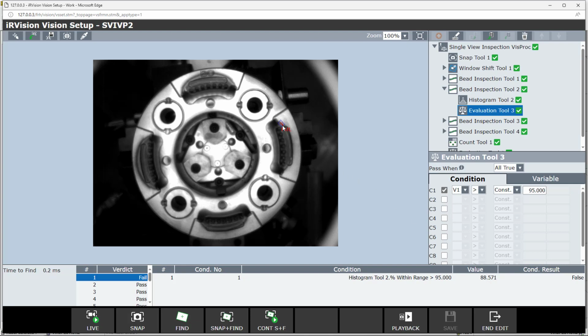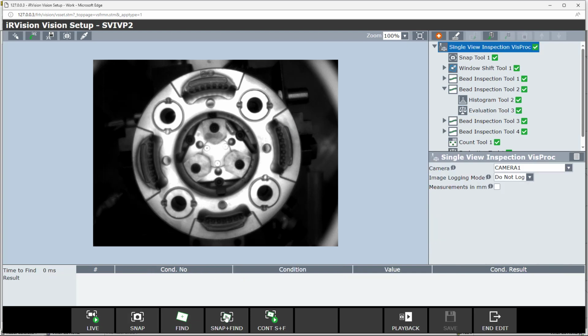And also you can see that the heat treatment is not exactly the same as the heat treatment that we have on the other areas, where it is taking a little more of the area, and here it is very limited. So probably this will be a part that is going to fail anyway. Probably the coil for the heat treatment was a little shifted. We're going to take another snap and find.